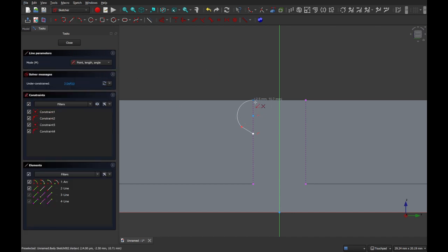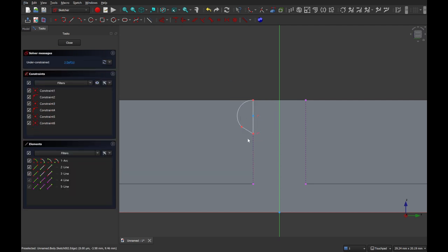Don't forget we have to actually now draw in this line there to close the sketch. Just to make it look nice, you'll want those two to be tangent, so it's a nice transition from the arc to the line. But what we also want to do is constrain that angle to be 45 degrees. There. So now you've got a bump that can be printed without supports. So you don't have to worry about that.